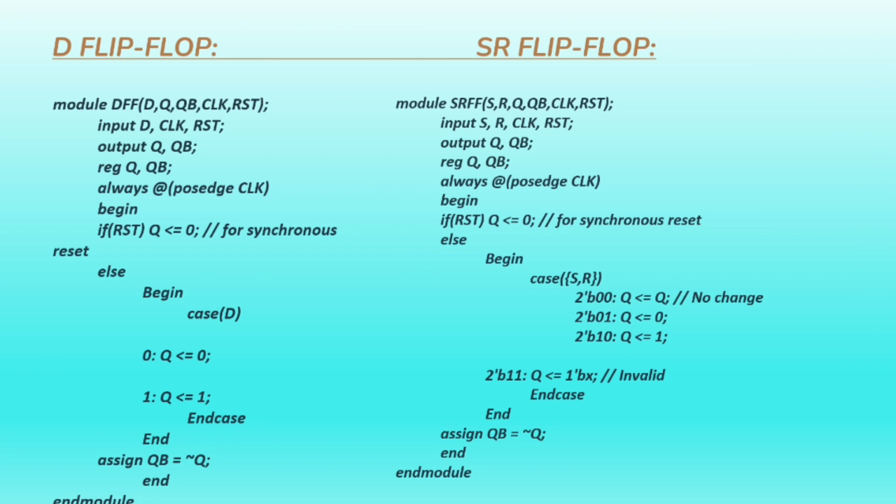A D flip-flop is a better alternative that is very popular in digital electronics. They are commonly used for counters, shift registers and input synchronization. In the D flip-flop, the output can only be changed at the clock edge, and if the input changes at other times, the output will be unaffected. The change of the state of the output is dependent on the rising edge of the clock. The output Q is the same as the input and can only change at the rising edge of the clock.